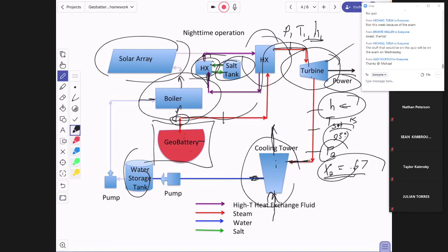We know that it's coming in at, what do we say, that we're looking at this thing as being at an enthalpy coming out at 2808, and we've got an enthalpy coming in at 104.89, right? So we already know what that would be. And so those are the kinds of things that you really should feel comfortable with at this point. And if we have these down, we can do the energy balances. And if we can do the mass balances, then the rest of the stuff starts to flow.